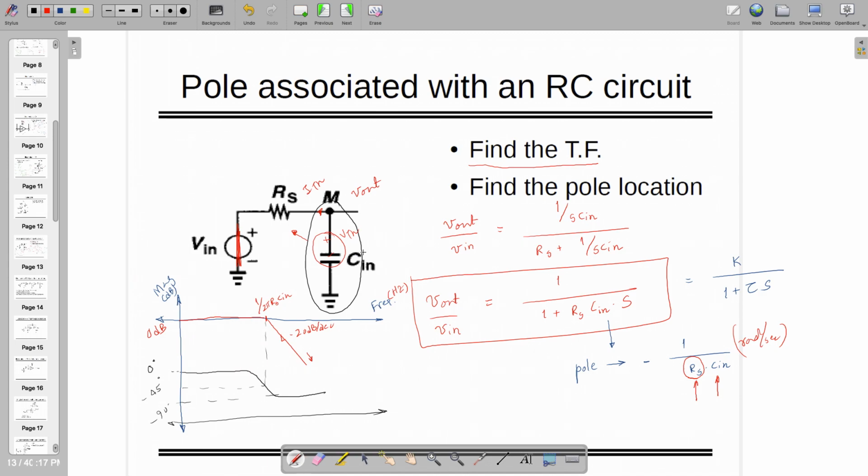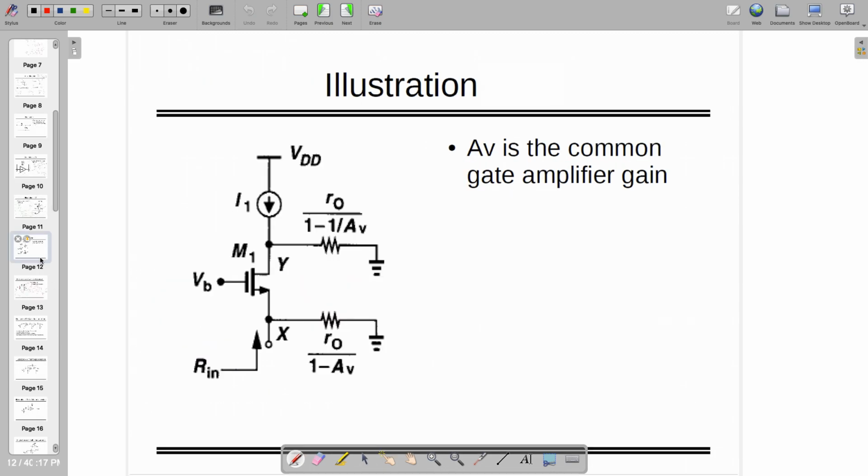That is a very crucial thing. So if there are some other capacitors also given or going to the rest of the circuit, you don't have to consider those as open circuit, right? Those are also the possible voltage source. You need to make them 0 at that time. So those are not there, or accordingly you can remove it. So we need to find out only for the capacitor which you are working on. Okay, so